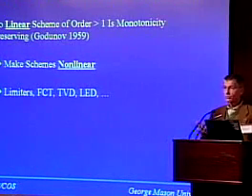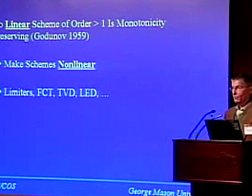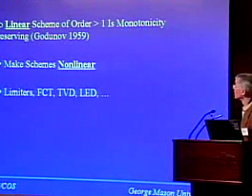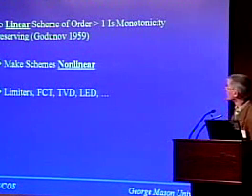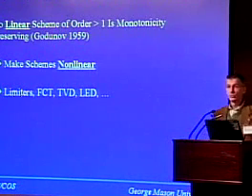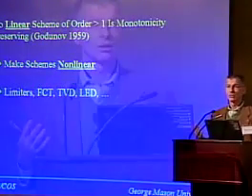Let me show you a couple of aspects as to what has happened in CFD over the years. In 1959, there was this theorem of Godunov that no linear scheme of order higher than 1 can be monotonicity preserving. This is a devastating theorem, if you think about it. So any scheme that you take that is linear by its very nature, most of the schemes that were out there at the time, none of these would ever be able to go beyond first order accuracy. And so it took about 10 years before people came around this and constructed nonlinear schemes.